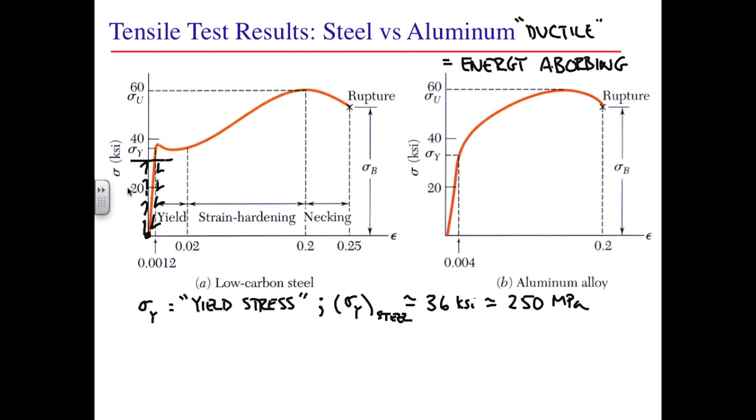If we increase the load on the material beyond its elastic range, that is, above the yield stress, permanent irreversible deformation occurs. It is observed experimentally that if we impose a stress or strain beyond this elastic limit and then unload it, the specimen unloads elastically. That is, it unloads along a line parallel to its linear elastic response, leaving a permanent deformation when it's completely unloaded. Suppose, for example, that we were going to impose a stress at this level above the yield stress.